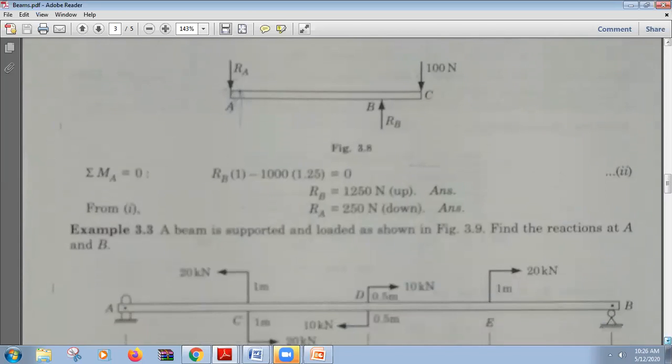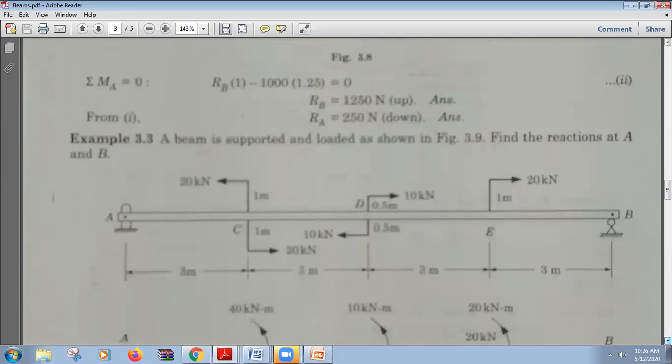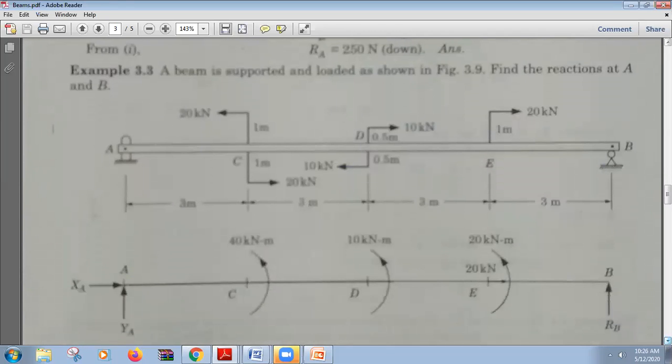So another question is there. We can see this is pivot, a fulcrum about which this beam can rotate. So we are having two reactions. Actually, I told that in case of pivot or fulcrum, we have an inclined reaction. So this acts like this. So this is a combination of vertical and horizontal reaction.